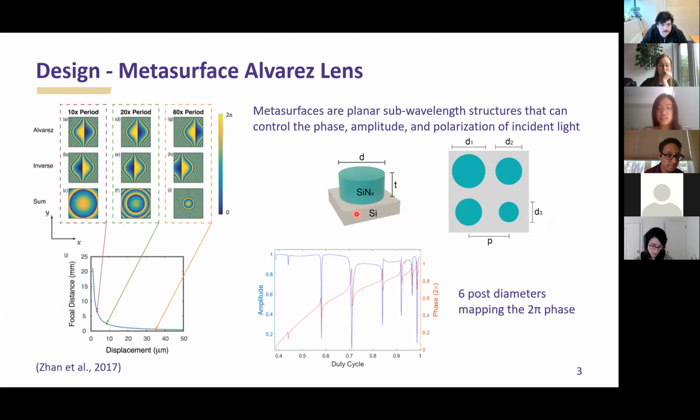Okay. So in order to reduce the 3D geometry of the lens for ultimate miniaturization of devices with high performance, metasurface optics have been developed. Metasurface optics are planar sub-wavelength structures that can control the phase, amplitude, or polarization of the incident light, and can hence mimic complex geometric curvatures on a flat, usually wavelength-scale surface, which means a couple of microns thick.